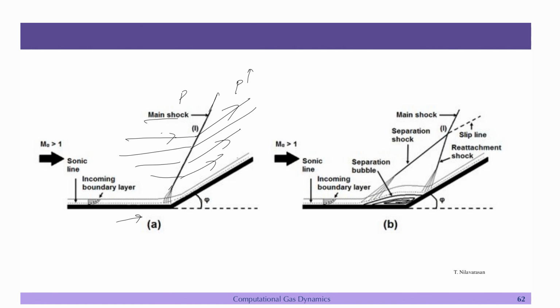This has to negotiate with the boundary layer, and because of that a separation gets developed due to this shock and boundary layer interaction. There is a shock here, there is a boundary layer, the field is viscous, and at least near the wall, near the viscous region, it is not obeying the hyperbolic law, it is obeying the elliptic law where the information can travel every side and every place. Then you will see a separation region being formed.